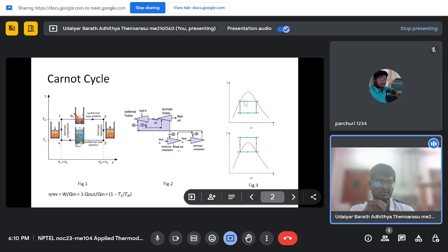So one thing you can say is, I'll put it above the dome like this, which is shown in figure 3 below. So you are able to overcome the two-phase problems, and the other is the temperature; you are utilizing the temperature. But the problem here is that the pressure at which you are operating will go very high. As I told, the critical pressure is 220 bar. 220 bar is a very big pressure, and if you are operating at a higher temperature, your pressure becomes even higher. So that can be another problem which can happen here.